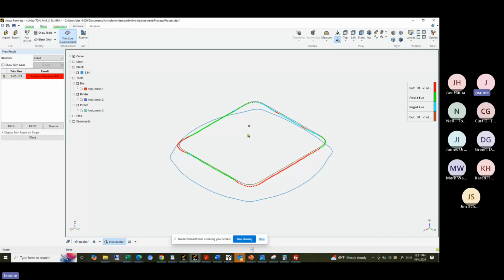This is already a run. It will show you the initial run. You have point weighting tolerance of only 26%. The red color shows it's off the tolerance. Green and blue are within tolerance. Green is a little bit too large, and blue is a little bit too short. That's iteration one, the initial iteration. In the next iteration, you got a 93% match. Once it was 93, I stopped, so there's no result for iteration two. If you have time, you can continue to make it near 100.